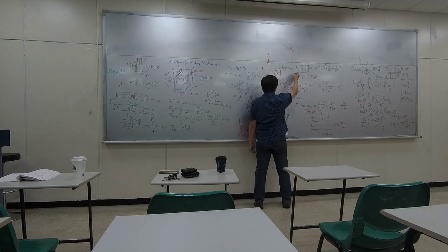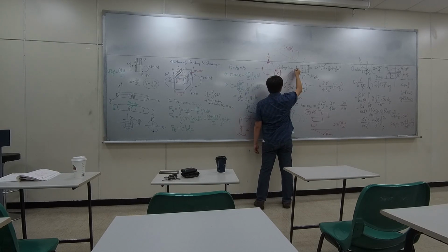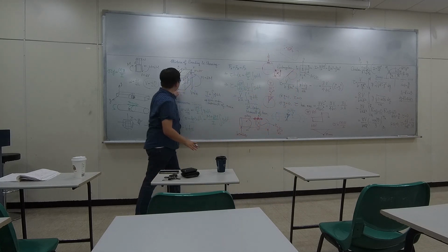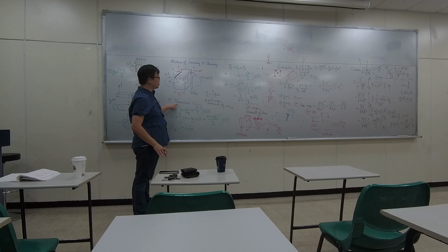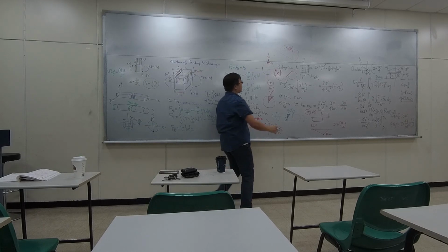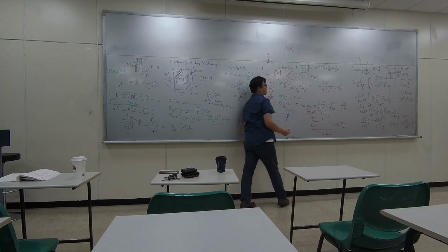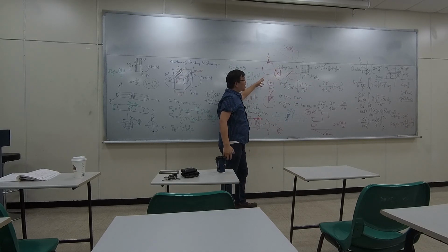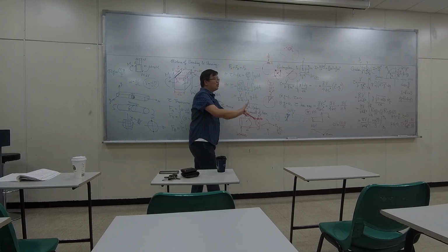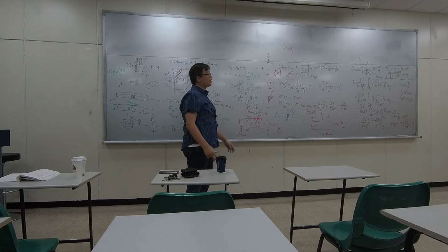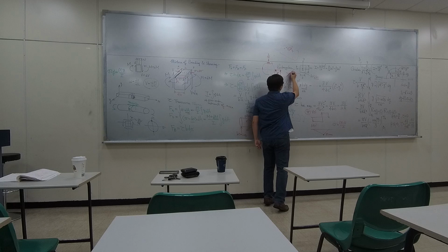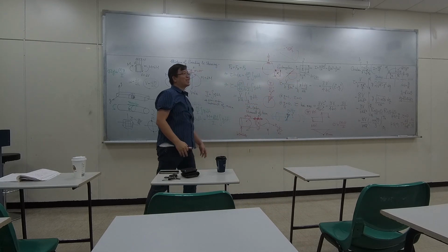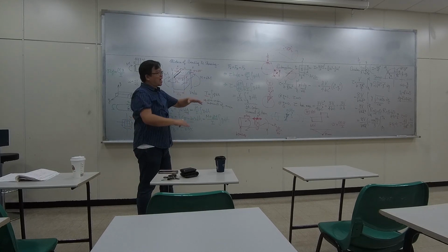So it's like you are working on a particular coordinate, like a working plane. However, when we are studying transverse shear, we are studying in a horizontal plane. So they are forces or stress on different planes. You cannot directly sum them up. So on this particular point, it's no longer a plane stress problem because you have stress outside of the plane.